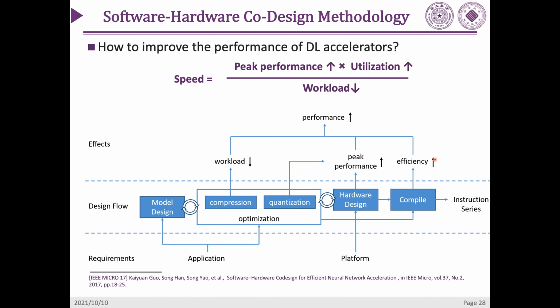The efficiency mostly depends on the compilation technology and the memory design. And the workload mostly depends on the compression and the quantization, because after quantization, the bandwidth requirement will be lower. So these are the key points you may need to understand.